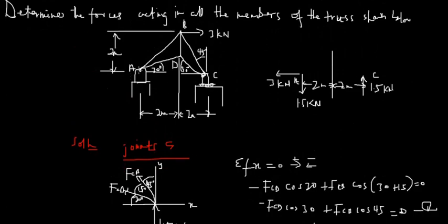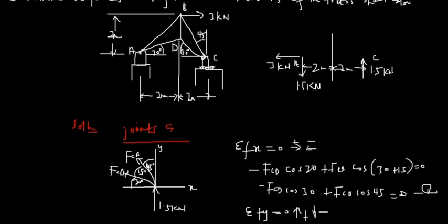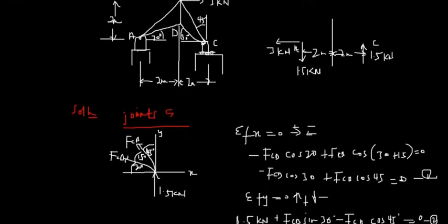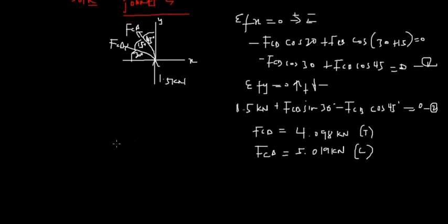So we are taking what? At point A. We already know all the forces at point C, so most definitely they might be quite opposite to A. So let's take point D. Let's take the forces at point D. For point D, or joint D, let me draw the free body diagram first.